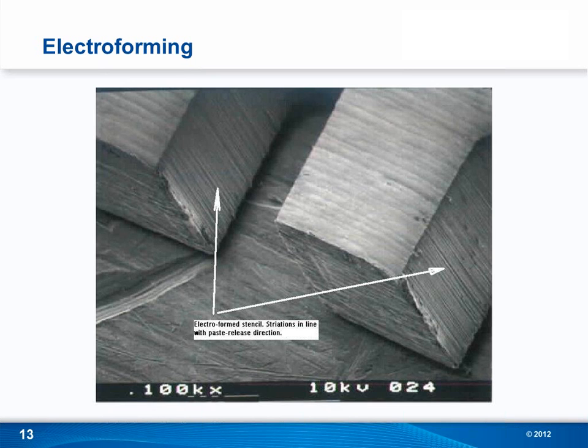From a performance point of view, we have always been very close to the performance that you can expect from an electroformed stencil. Additionally, there are processes called electro-polishing, and I have found that those don't make a significant improvement, or any improvement at all, when it comes to paste release. So chemically, it's out.